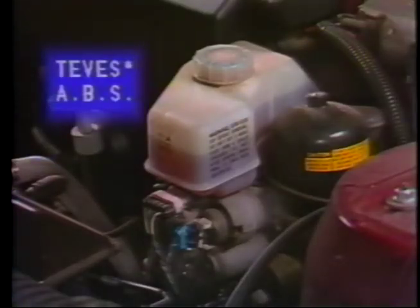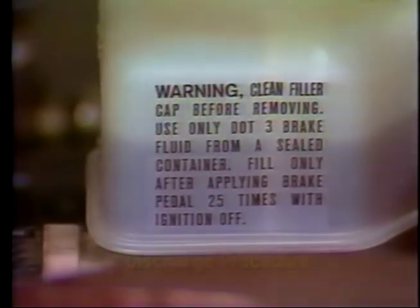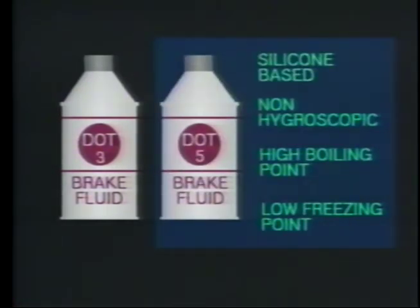Because Technician A used the phrase on most vehicles, his statement is true. On most vehicles, you do check the fluid level with the accumulator discharged. But always check the label on the fluid reservoir to be sure, because there are some vehicles in which you check the fluid level with the accumulator charged. Technician B's statement is false. Although most vehicles with Teves anti-lock brakes recommend DOT 3 brake fluid, there are a few vehicles that recommend DOT 5. Our technician, however, stated that you should always use DOT 5. The correct answer, therefore, is response A.